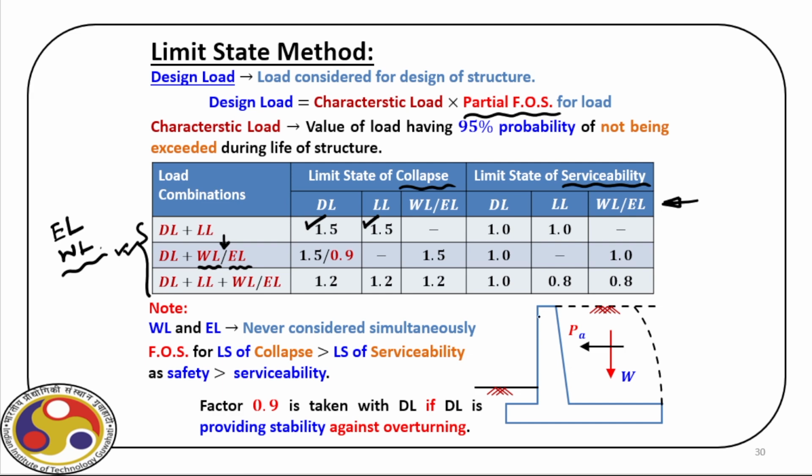Now, for example, say we have a retaining wall. On one side of this retaining wall, we have this soil mass, and the wall is supposed to take care of this soil mass. There are different types of failure that may happen. It may topple over this point, it may have a failure at this point, or it may altogether slide along this direction, because active earth pressure is acting over the wall and it may slide at the base. So these are the different types of failure we have to consider.